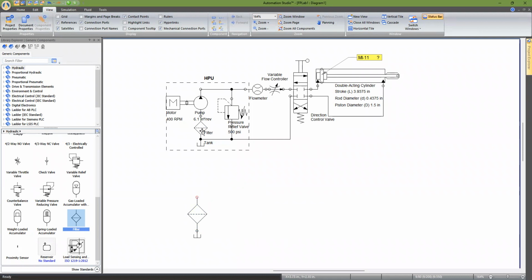Now, this one looks a little bit smaller than this one because I changed the size of this component, which you can also do. You select that thing, and then you have to unlock, as each component is locked for its size. If you press that, this becomes unlocked, and now you see those marquees around this rectangle, and you can actually change the size of the component to whatever you like. And whatever you do, the connection will follow you, so it will not get disconnected while you are doing that. So bring that back to where it was, just something like that, and then it looks much more similar to this one.